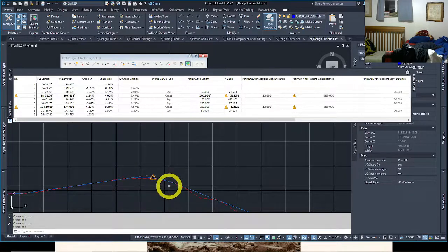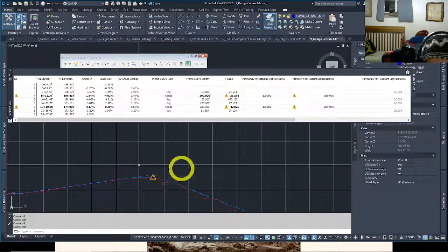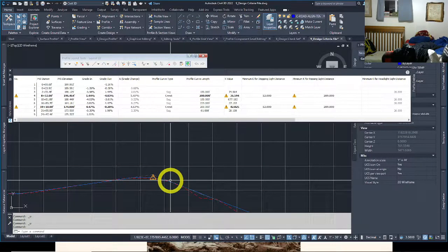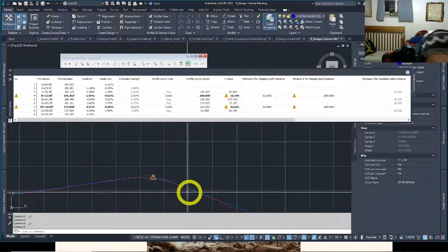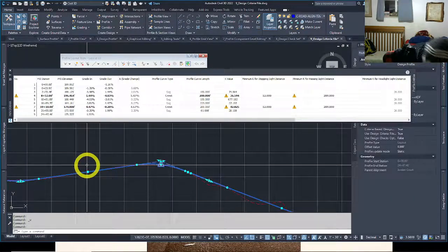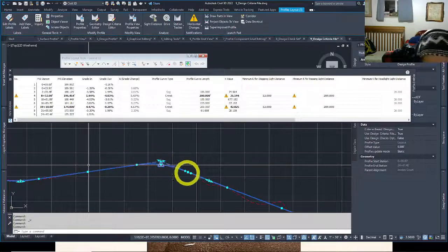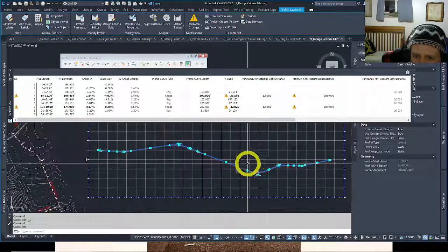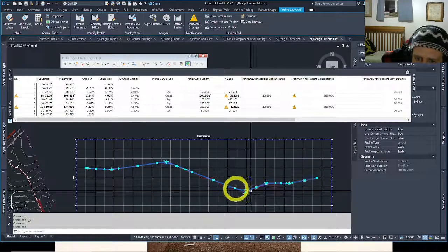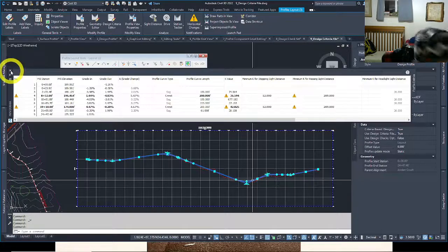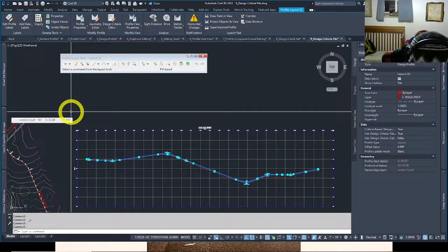There's a certain acceptable distance that varies based on the design speed. If you're going faster, that's more critical than slow. All of it has to do with design speed on headlight sight distance and safety enough for the driver to react. So those all come into play along with the K value, the vertical abruptness of the curve. Those two are big factors in highway design. That is the end of chapter 7. We'll continue on chapter 8 soon.